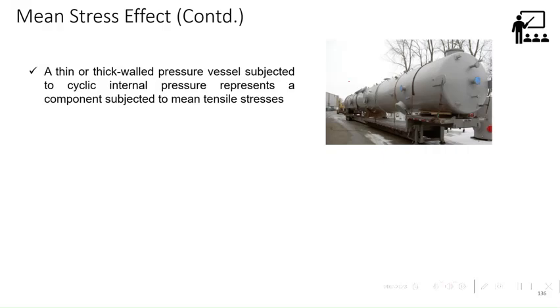But once it is exhausted, you give it for refilling, and that is one cycle of pressure cycling. But as long as the gas is compressed inside, it will always be in tension. There is no fluctuation, but one level to another level is coming, but they are static loads. But the cylinder is subjected to cyclic loading when it gets emptied and refilled. That will be one cycle.